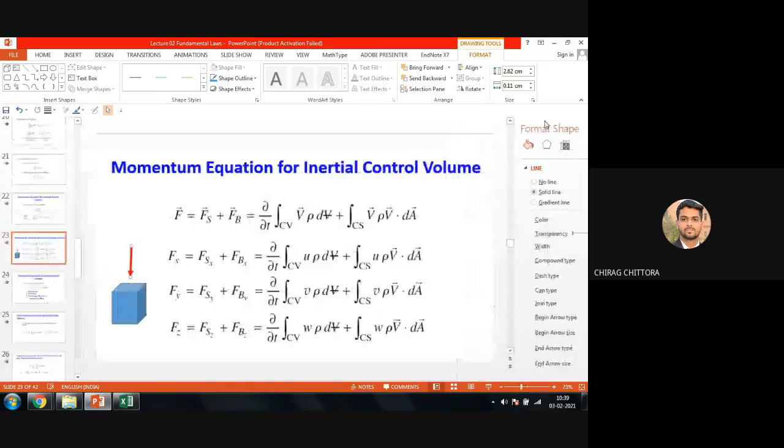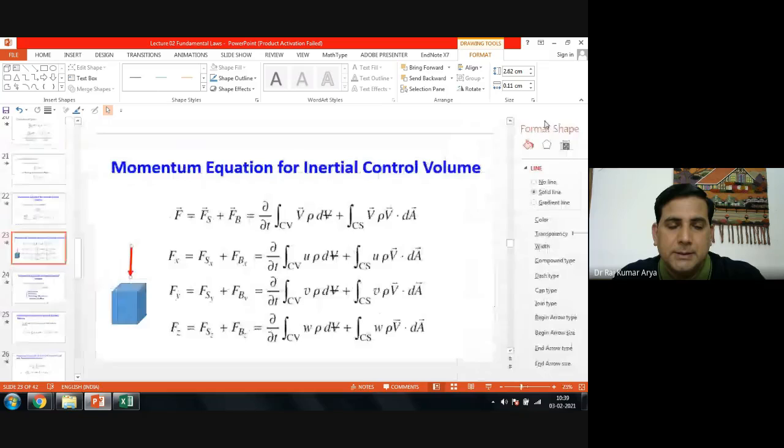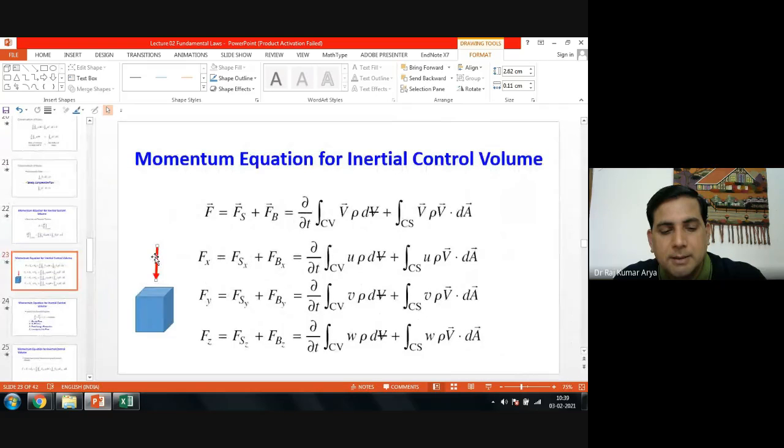Yes, sir. Now you can change this to a different side. Maybe you can apply a force in the reverse side, maybe this side. This is one of the ways. So this force will provide a compressive force and this one will provide the expansive force. A compressive force normal to the surface will give you your pressure, right? And this would give you the volume dilation, the expansion part. This will try to expand it, so it will actually give you stretching.